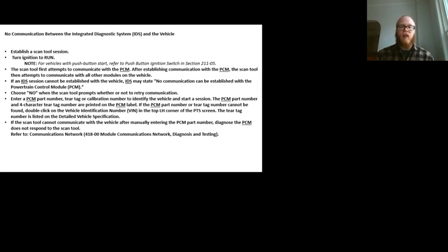It knows model year, manufacturer, place of manufacturer, is it even four-wheel drive, what size engine's in it, all kinds of information. So if that doesn't work with a Snap-on scan tool, we're pretty lucky because we can just go in usually by make, model, year, and that's kind of like a backdoor in there for us.